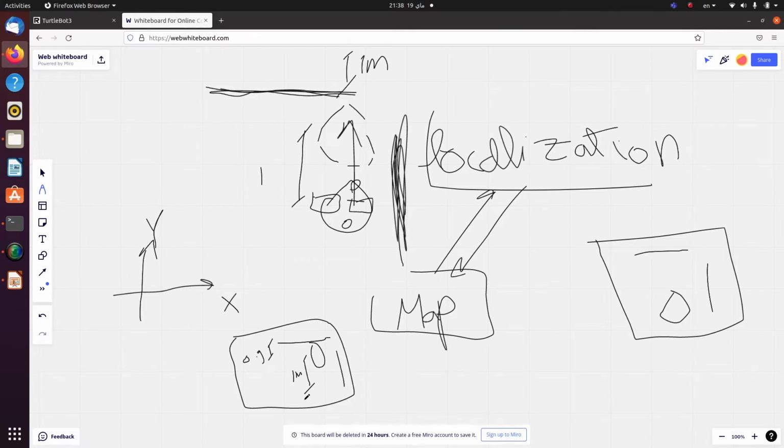So through some sensor fusion paradigm, I can now say that the robot moved a distance with an estimate that is better than both the individual reading of the LiDAR and the individual reading of the dead reckoning sensors. So I'd say that I moved like 0.95 meters, for example, relative to my first location.